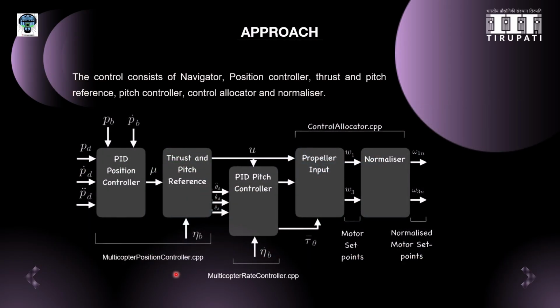The control system is built as a cascade of controllers. At the top level is a position controller that determines where the drone should go. Normally, it would command roll, pitch, yaw and thrust. In this case, the position controller outputs just two references, one for vertical thrust and one for pitch angle, ignoring yaw. The pitch controller is a custom PID control loop that tilts the drone to the desired pitch angle. Meanwhile, a thrust controller, another PID, adjusts the total upwards thrust to control the descent rate.